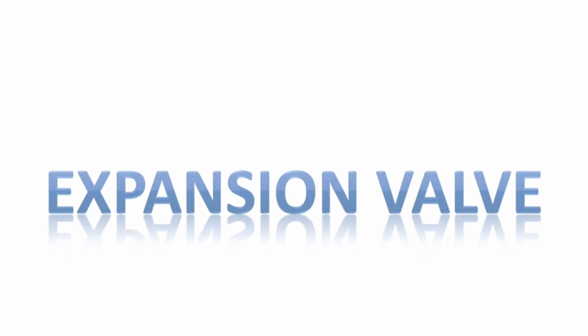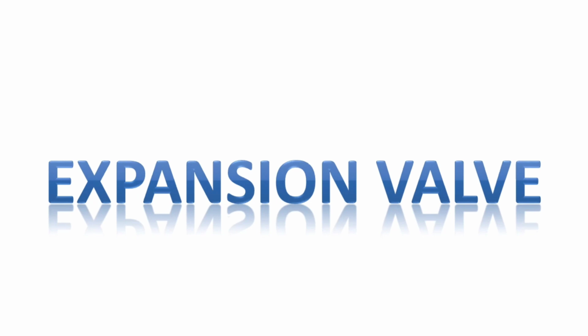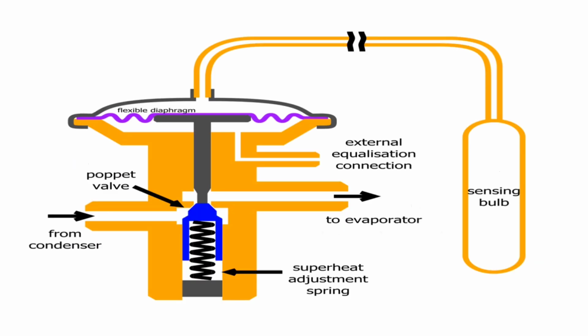Now, the next one is one of the most important components in the refrigeration system, that is the expansion valve. The thermal expansion valve or thermostatic expansion valve is a component in an air conditioning system that controls the amount of refrigerant released into the evaporator and is intended to regulate the superheat of the refrigerant that flows out of the evaporator to a steady value.